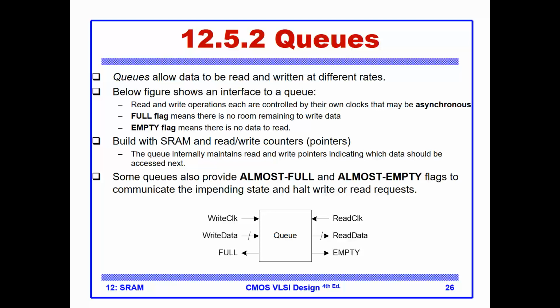And then here what we have finally in terms of these storages which have some kind of order to access the data, we get into finally the queues. The queues are very important hardware structures when we communicate with systems, in particular if those systems are asynchronous. Typically you will have a producer of data sending data to a consumer of data, which consumes the data. And the producer could be a sensor, and the consumer could be a system which reads the sensor.